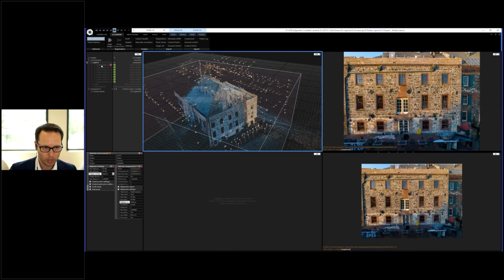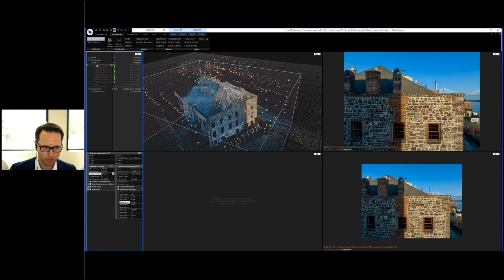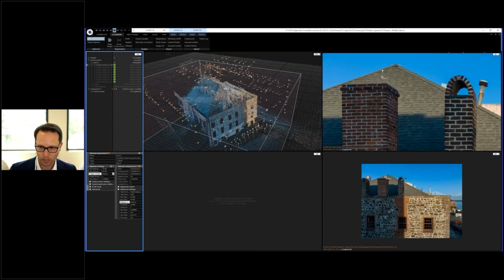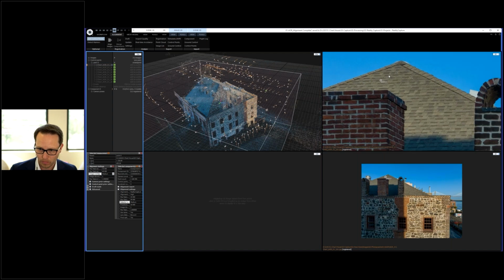Right, so this is point 0. You created control point 0, and that pixel that I picked is in all of these images that are listed. What we're going to do first is select one of these images and try to find an easy to spot point that we can pick in all of those images. Usually I pick points that have some high contrast.